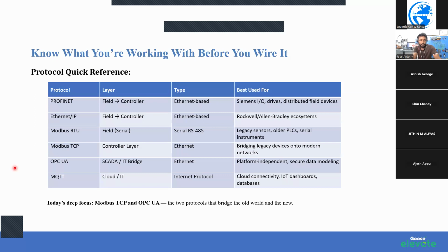And we have OPC UA and MQTT. OPC UA is a newer addition to the industrial communication protocols, and it is mainly used to communicate between the controllers and systems outside the controller, like ERP stations and MES, manufacturing execution stations. Why? Because OPC UA is released as an open protocol, and in recent years we can see that most controllers are equipped with OPC UA. Because of OPC UA, we avoid a lot of licensing costs, and simplicity of development is an advantage.